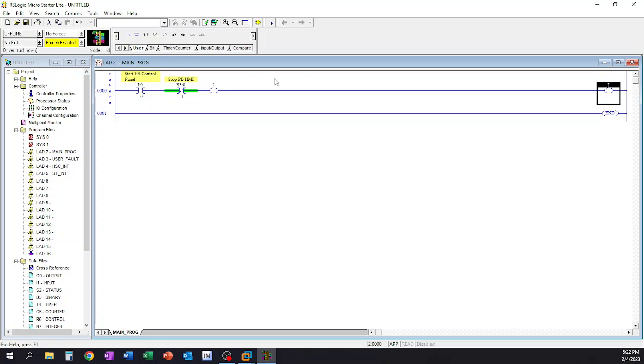But the OTE is simply an output function, and in a standard wiring world, this would be considered our coil, our output. So in the PLC, we're sending the output power to this particular coil, drive, relay, whatever it might be, a light, who knows.